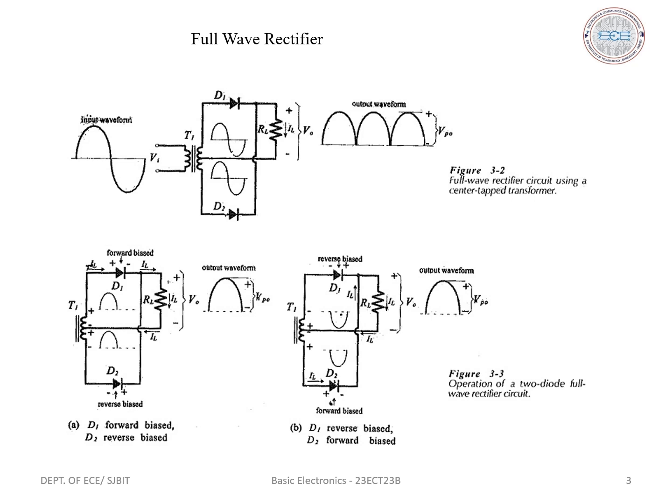In this circuit, the secondary winding resistance is formed by two series resistances, and C1 charges very rapidly as soon as D1 or D2 starts to conduct. Here the load resistance is very much larger than the resistance of the secondary circuit, hence the capacitor takes more time for discharging. During this time D1 and D2 will be reverse biased and in the non-conducting state. Therefore, the only discharge path for the capacitor C1 is through the load resistance RL. So this is how the full wave rectifier works.